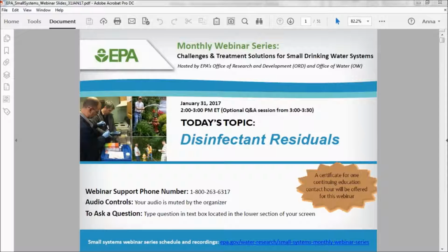Any water that contains natural organic matter, and all do to some extent, and natural organic matter that contains very small amounts of nitrogen and ammonia, when you chloraminate, some of that will get tied up with these organic materials and be basically organic chloramines that show up in your total chlorine tests, but don't necessarily add disinfection power. And so that could be a tenth or two in your total chlorine analysis, and oftentimes that's why a total chlorine analysis will be 1 or 2 tenths higher than the free chlorine analysis.